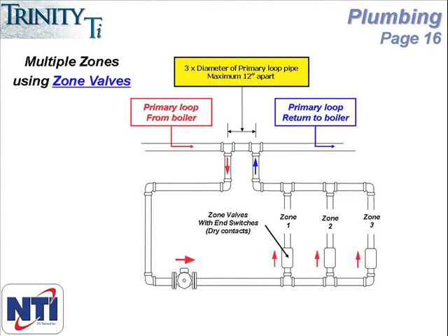In terms of how to lay out the piping for the secondary, it's really up to the individual installer and determined by the needs of the particular job. The installation manual lays out a couple of the more common ways of laying out the secondary and shows how it's attached to the primary loop using the closely spaced T's we discussed earlier.